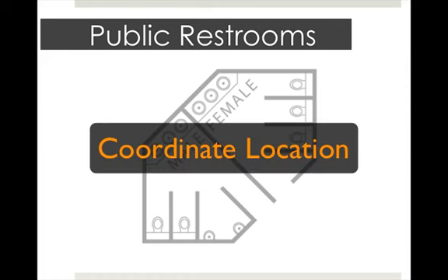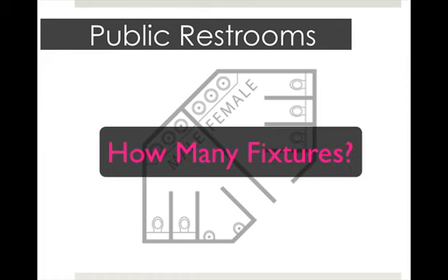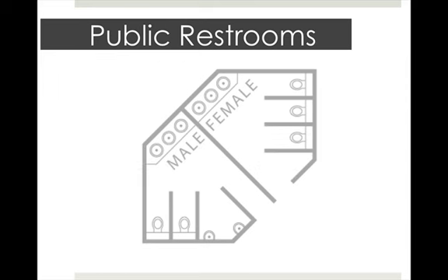They will need to also be coordinated with the building's mechanical systems, which of course will influence the location of the bathrooms. And codes not only dictate the spacing of the facility and the clearance requirements, but also the number of facilities and privacy requirements as well. So depending on the occupancy, you will be required to put 1, 2, 3 toilets. That'll also dictate how many sinks you have and how many urinals you have, and so on and so forth.